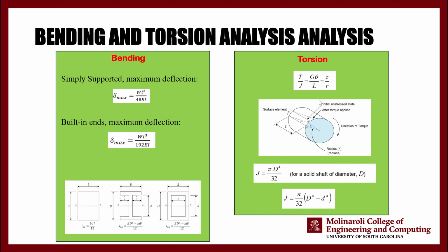For the torsion parts, you are going to be given a hollow cylinder and a filled cylinder, and a rod, essentially, a hollow rod and a regular rod, and a different radius rod. But the thing is, all of these are going to have the exact same material, and then you're going to apply a load, torque to your system, and you can calculate the polar moment of inertia using these two equations.